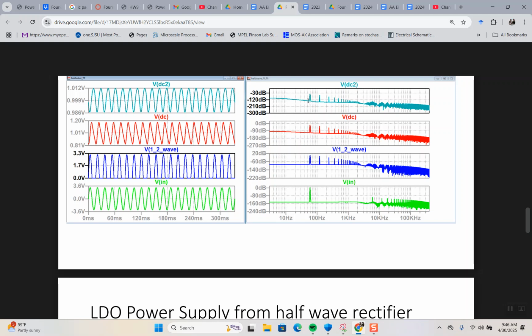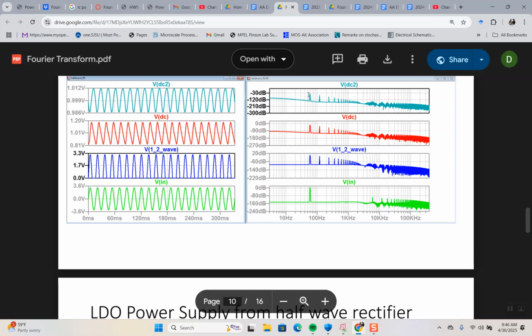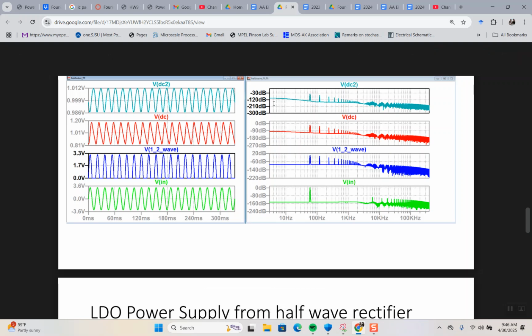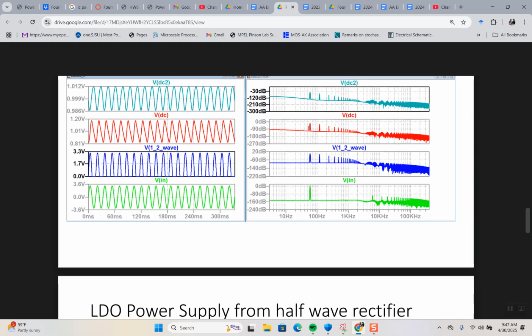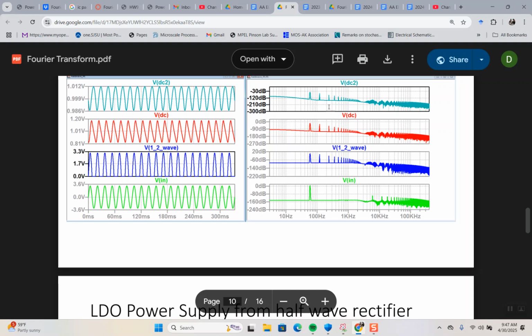And then the final, the harmonics again are still there, but I should say, LTspice won't give you the DC part. It gets rid of it. So what you're seeing is the first harmonic, which you don't want. You want the DC, right? So it's not showing you the DC, and then you filter it, and this peak, they all get smaller and smaller.